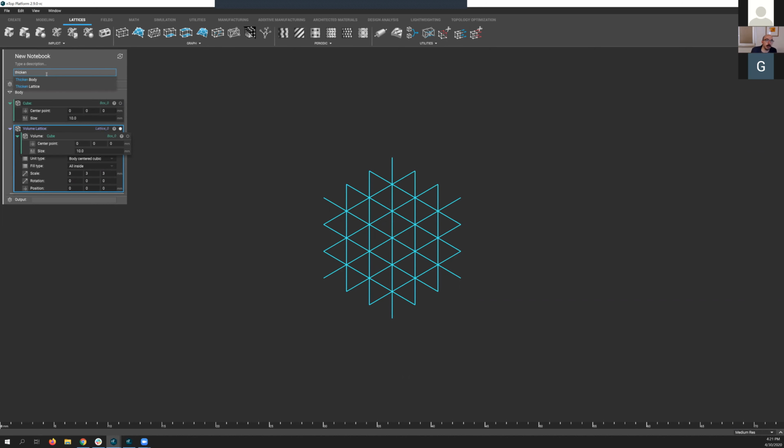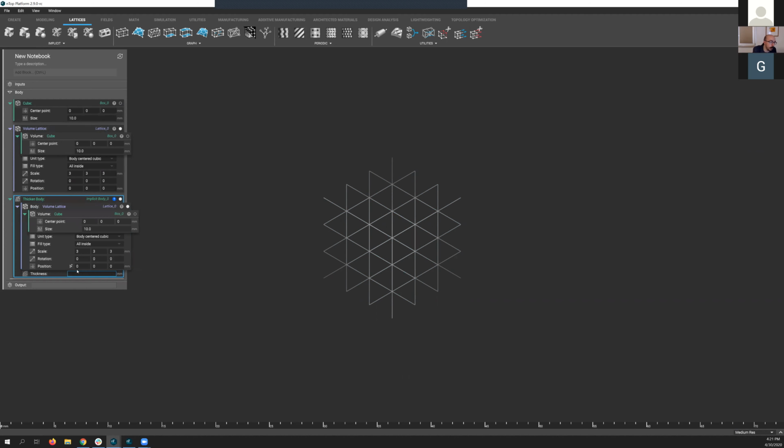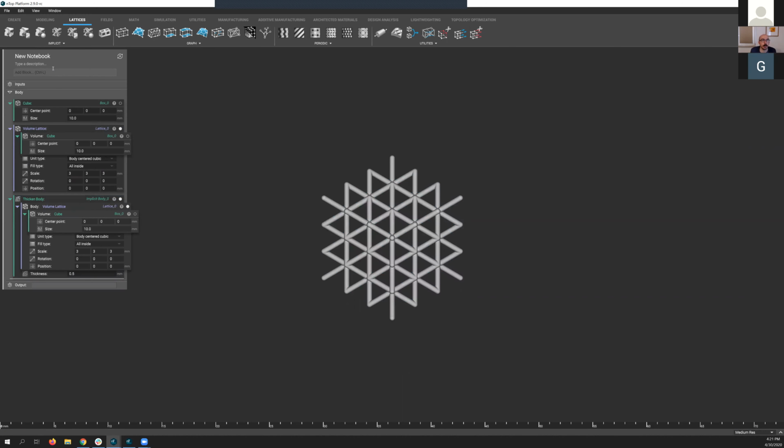As we generate meshes for this geometry, whether it's an STL file or a 3MF file, there tend to be small noise shells added during the discretization process. And so one of the things we've added is these new mesh utility blocks. If I go up and say merge, we have this ability for merge mesh, filter mesh, and split mesh.